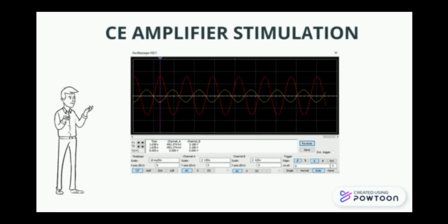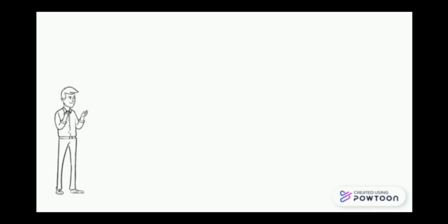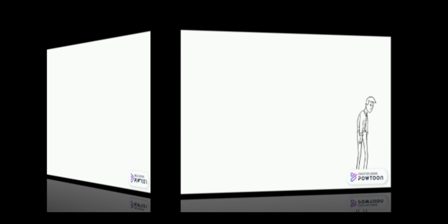Okay, now let's see our V peak. If we divide our V out by V in, we get a gain AV of negative 3.21. So it's not too different from the negative 4 gain, so we can say that our circuit is a success. Okay, that's all for DC and AC analysis. What we want to do next is frequency response. So let's go to my friend to explain more about frequency response.